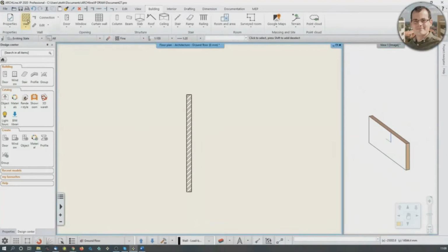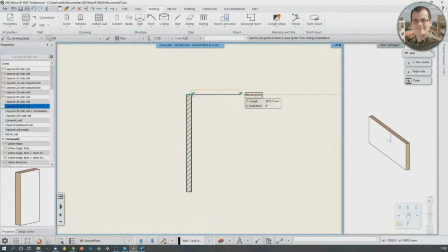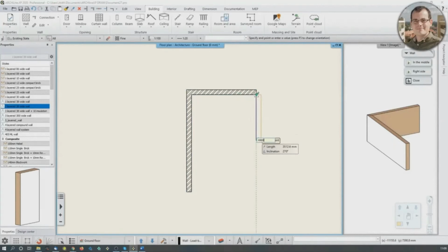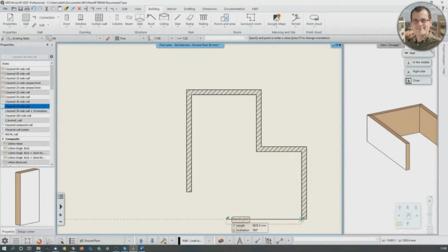Like so, we are just going to open up again the wall menu and draw the wall like this. Let me just use the cheat sheet. It's going to be 5,000 millimeters. And now we go again south, for the distance of 4,400, and another distance would be 3,500, and then we go south again, and that is going to be 5,200, and lastly we have the penultimate wall here for 6,400, and then I have a gap over here.